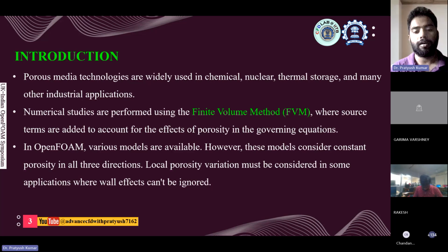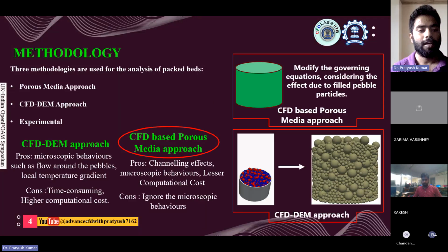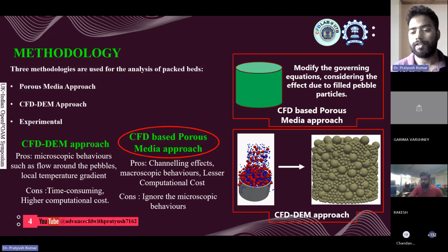Speaking of studying the packed bed, generally three approaches are used: the porous media approach, the CFD-DM approach, and the experimental approach. The experimental one is not related to the present conference. In the CFD-DM approach, we actually create the model. We have a given canister, we fill the canister with particles, and after filling, we create the geometry. After creating the geometry, we do the meshing, and after that, we do the CFD simulations.